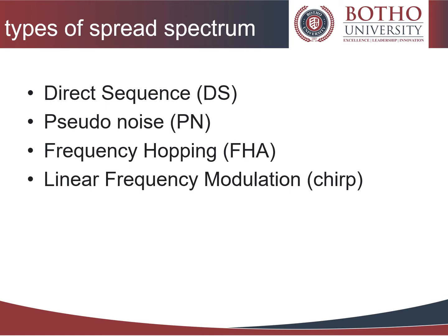The next one, which is called pseudo-noise, is where the pseudo-random sequence is referred to as the spreading code or a pseudo-noise sequence. The energy of the signal is equally divided among different frequencies. Frequency hopping, also known as frequency hopping spread spectrum, is a method of transmitting radio signals by rapidly changing their carrier frequency among many distinct frequencies, occupying a large spectral band. FHSS is used to avoid interference, to prevent eavesdropping, and to enable code division multiple access communications.